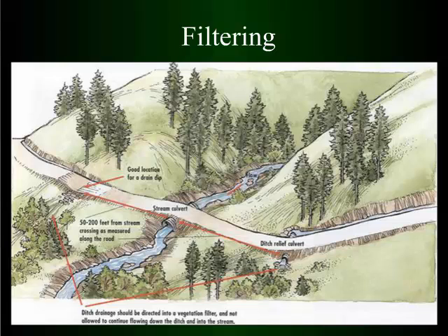Talked about rolling dips before. This is a situation where it's armored and water can come down the ditch line and cross the road in here. Mainly it's getting your ditch water out of the ditches and not directly dumping them into the streams.